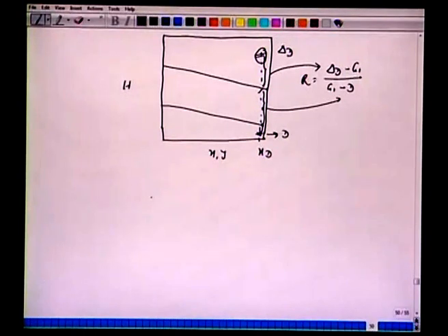Now let us say that the feed composition is known to us, and feed is saturated liquid. So we mark this XF and we mark this HF. We can always go from here, we can take this first tie line, we can connect with this, the second tie line, we can connect with this, and we can do extra, Y1, Y2, Y3, etc. Suppose we know HF and XF.